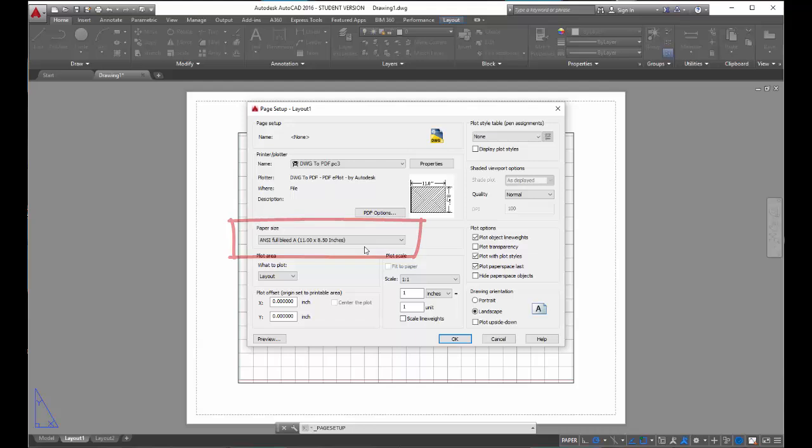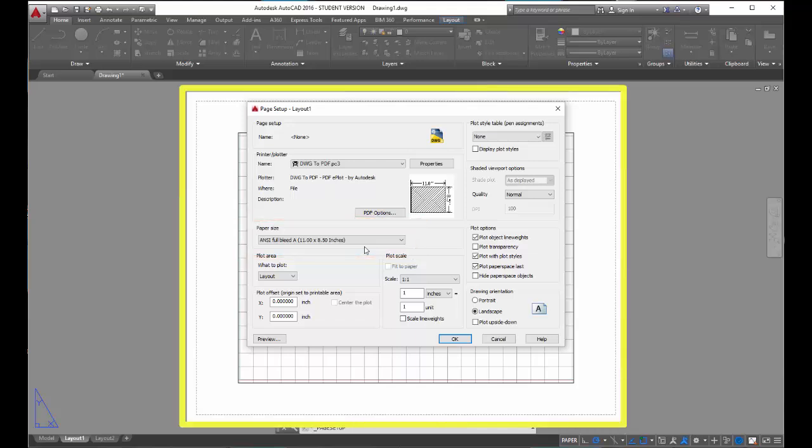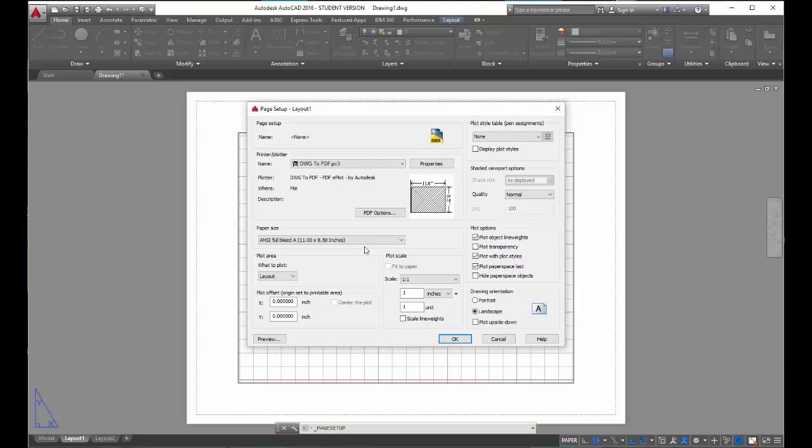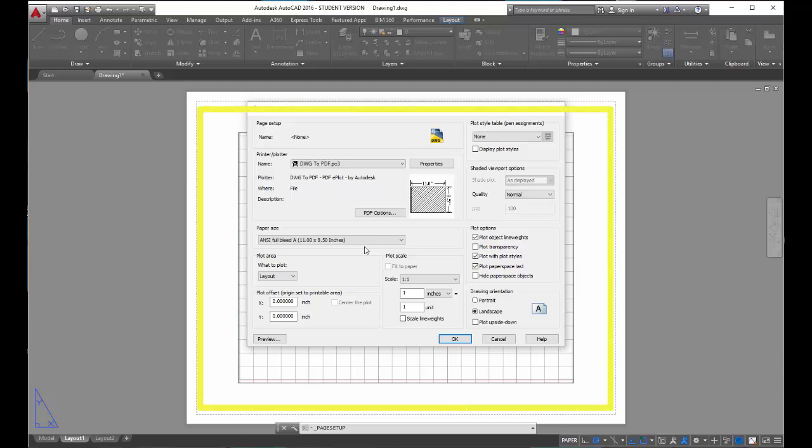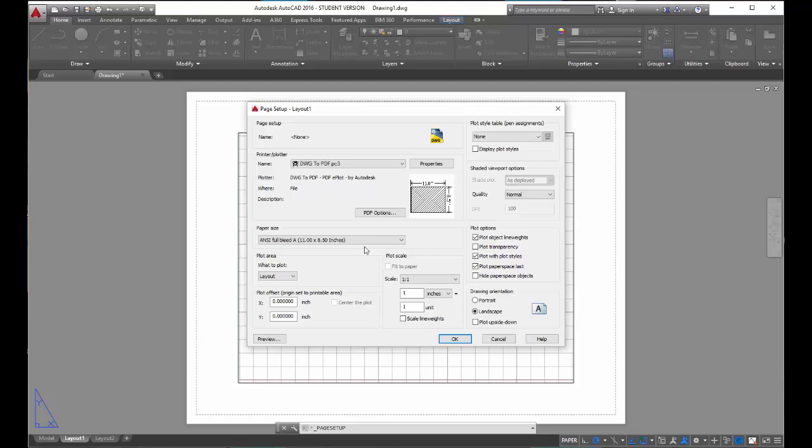with full bleed. Now what full bleed means is that the printing boundary is going to be closer to the edges of the white canvas than what they currently are. If we don't choose full bleed, the printing boundaries are located further away from the perimeter of the canvas. So my philosophy is that we want all the room we can get on a piece of paper so that we can fit our drawings on it. So important note is that the printing boundary is actually determined by the paper size that you choose. Aha!